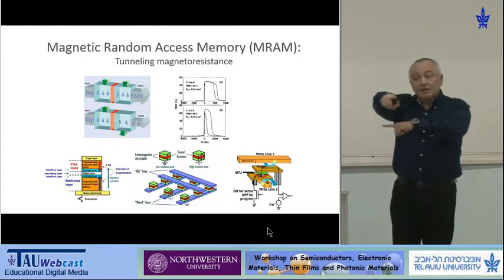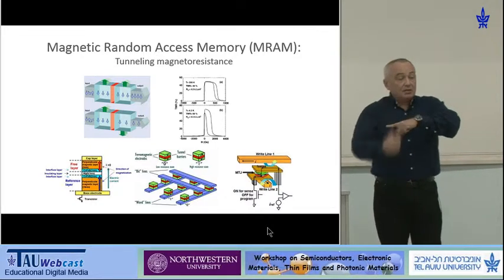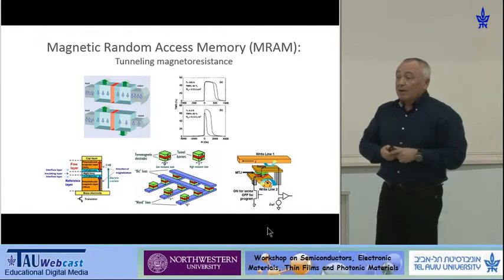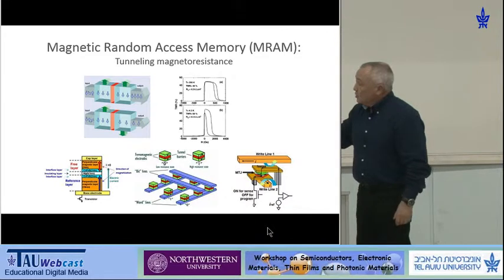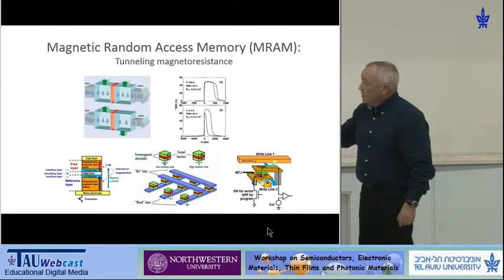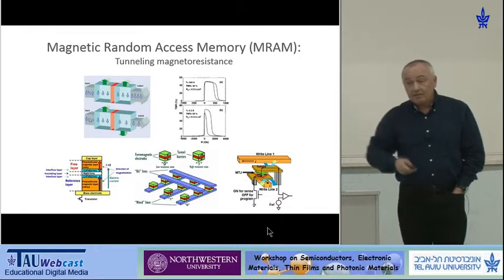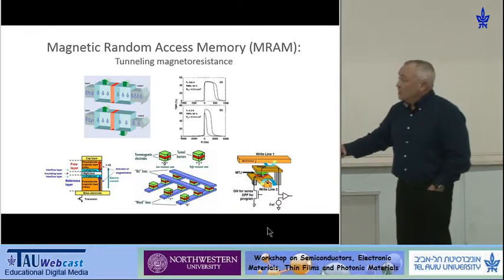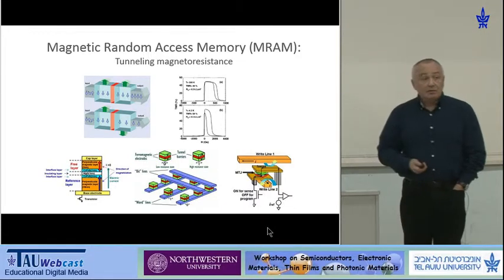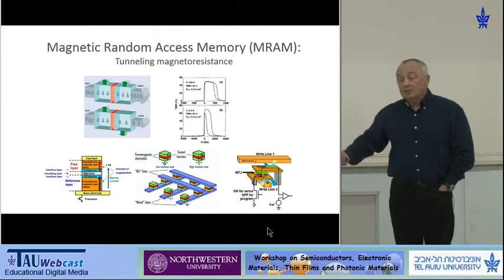But now the idea is that you can change the magnetization by pushing polarized current by spin transfer torque. That means that in order to write, you have to push here very strong currents in the range of 10^8, 10^9 ampere per centimeter square. That means that you generate high electrical field across this tunnel junction, and you kill it with time.